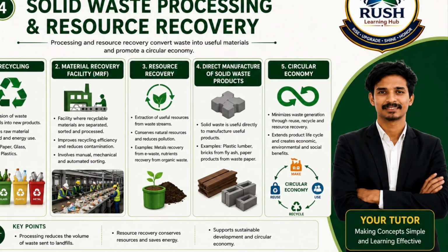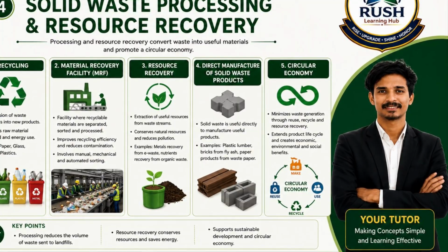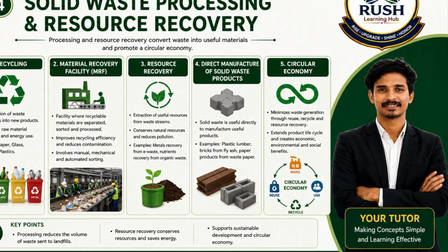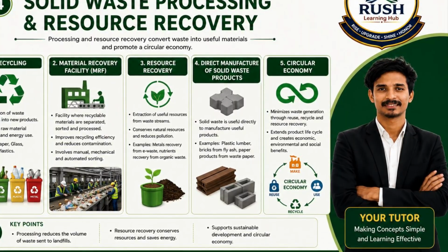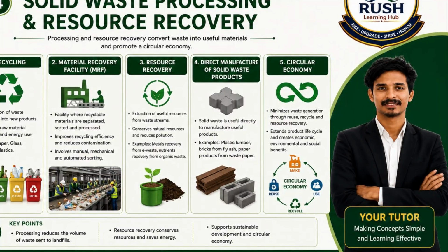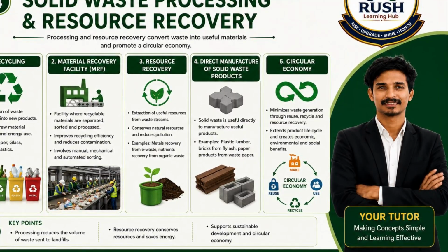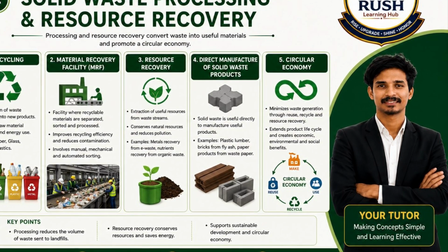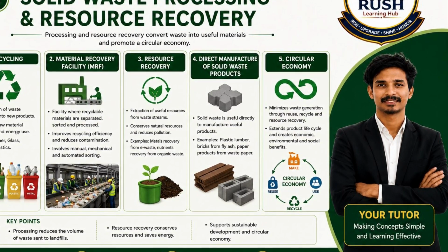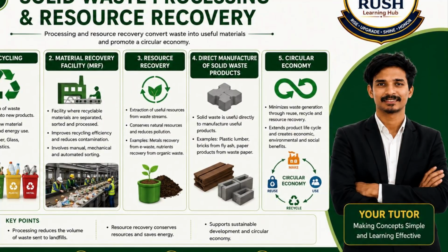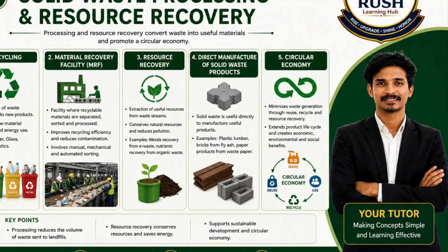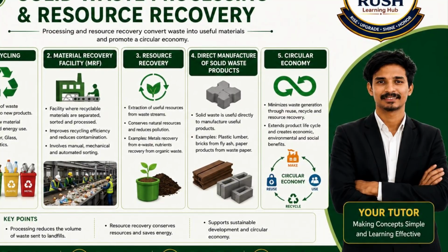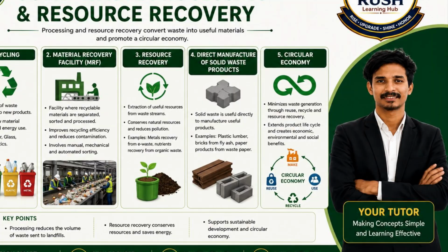Source segregation is always preferred because it improves recycling efficiency, reduces contamination, lowers treatment costs, and increases the quality of recovered materials. Now let us discuss material recovery facilities, commonly called MRFs. A material recovery facility is a specialized plant where mixed municipal solid waste is sorted and valuable recyclable materials are recovered before final disposal. Different technologies are used in material recovery facilities.